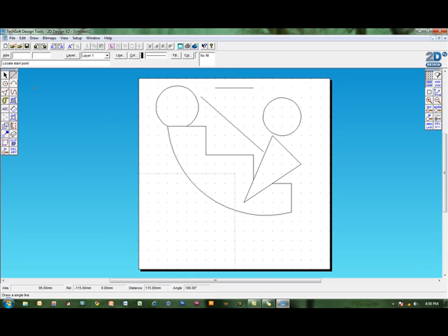So when I create a new line, it only happens when I create, you can see there, as I'm going across, hopefully you can see in the distance it says 40, so I know this is a 4 centimeter line. So instead of counting, because you don't want to do that all the time, you can see how far across it goes. Now if I drop it down 1 centimeter, it gives me an angle, and as well as that it says relative to where it started from, it's 4 centimeters long and it's dropped down 1 centimeter on my grid. So we know that it's actually got a centimeter drop, and you can watch those values change as I move it about. It will tell me my distance is at the moment 7.5, so it's 75 millimeters.